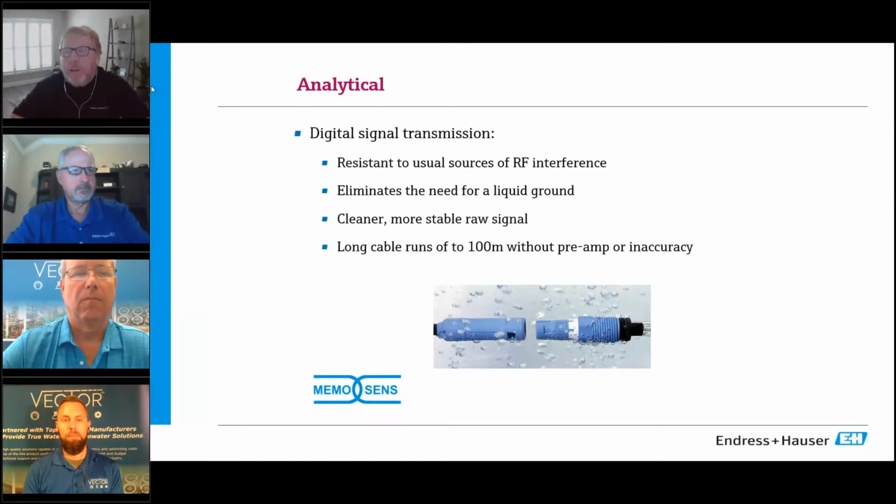So currently, we do not have NSF 61 approval on our analytical sensors. Now, there are reasons why, because a lot of these are monitored off a slipstream or bypass line, which is then dumped, so it doesn't go back into the process.